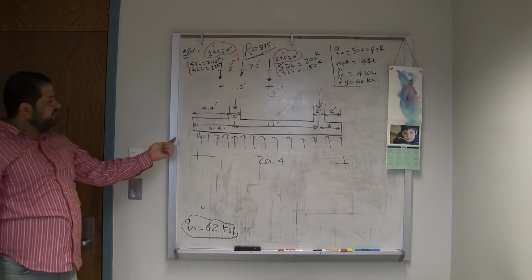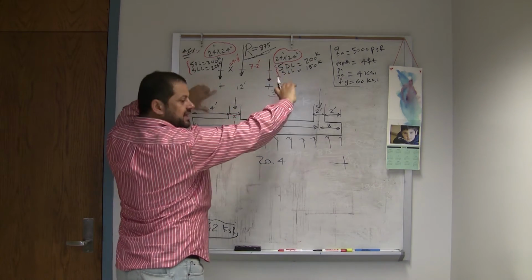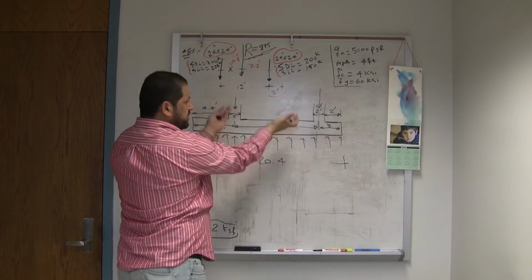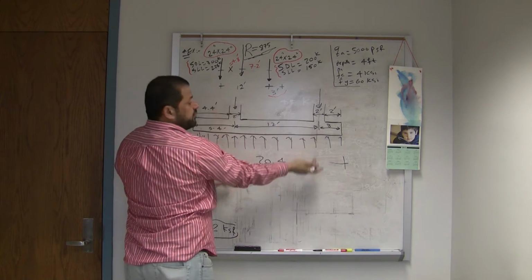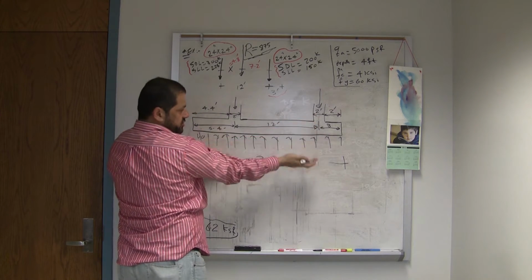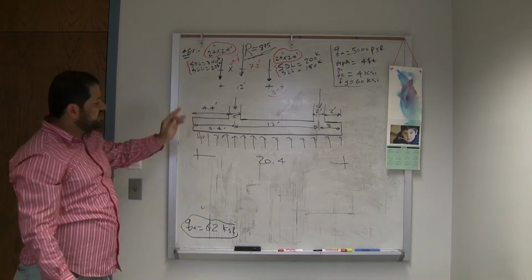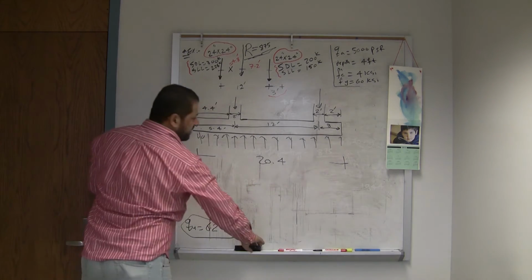So that's a beam. If you flip it, it becomes exactly a beam. Or you can look at it this way: now the columns are the support. The load is coming from the bottom, from the soil, and the support is the column. So it's just a simple shear diagram.